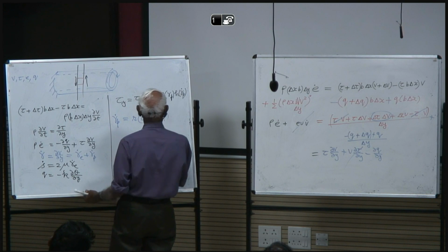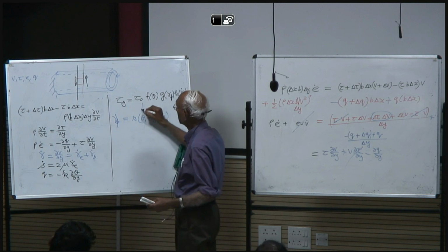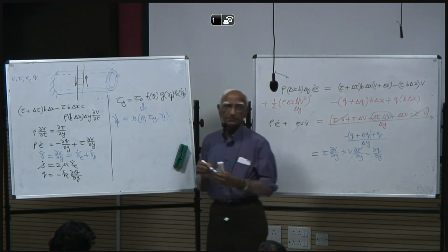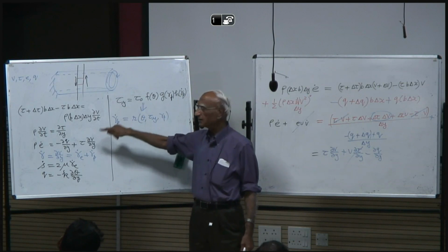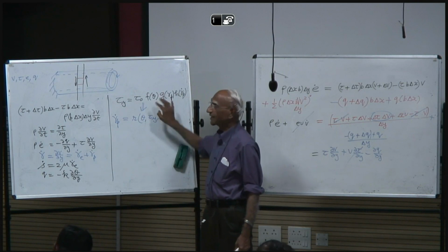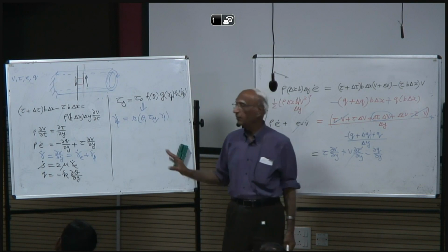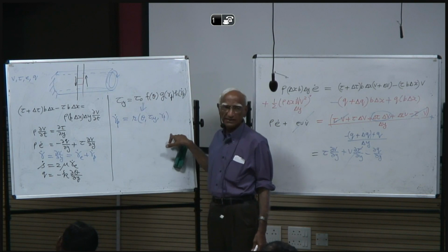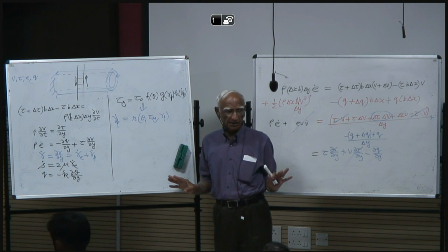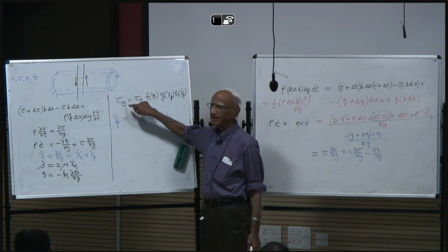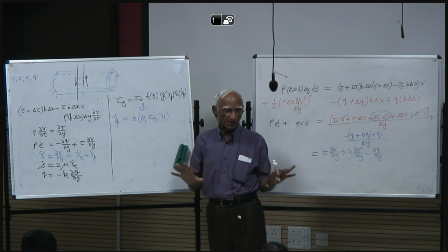So I can solve this equation. If my stress here, this tau, satisfies the yield criterion, I will solve this equation for this. Otherwise, it is zero. There is no plastic deformation. So if my stress is less than the yield stress, there is no plastic deformation.